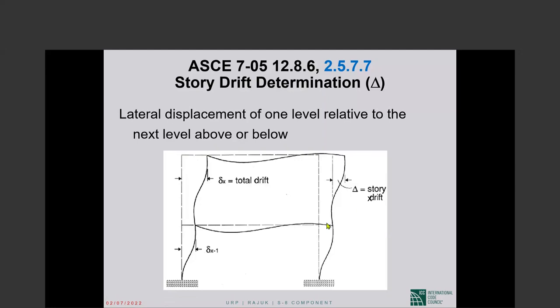The other place where we go beyond strict life safety is when we include an importance factor larger than one in design. That also takes us in the same direction of damage control and continued functioning of the structure during and following an earthquake.